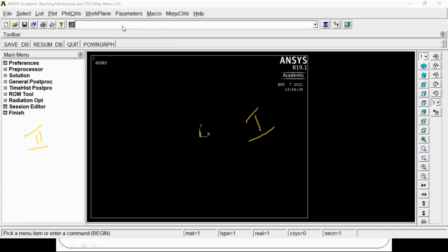And when you are making some calculations on the screen, behind the software, ANSYS is also writing its script. That's the log file. That is called as log file. You can download that log file, copy it, and paste it in the command prompt.